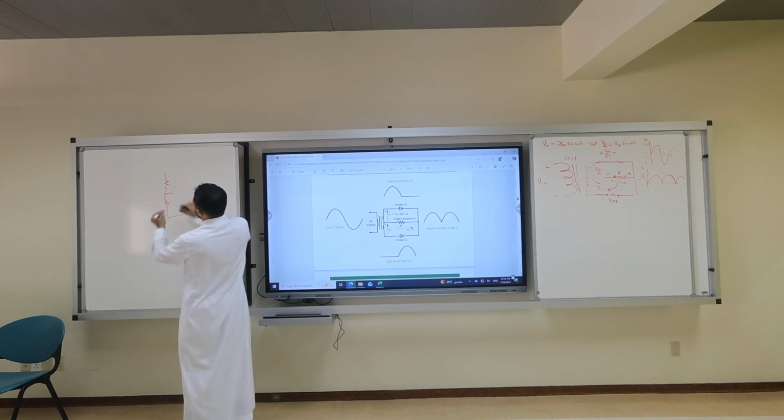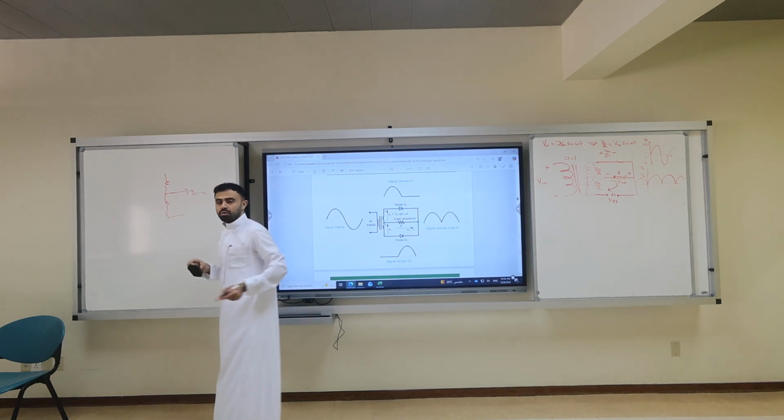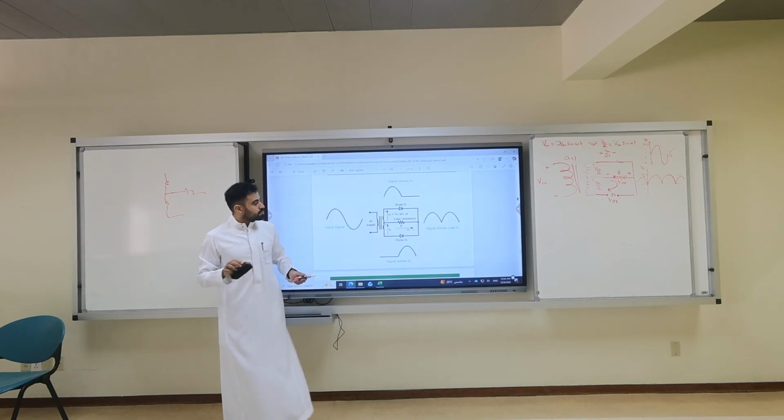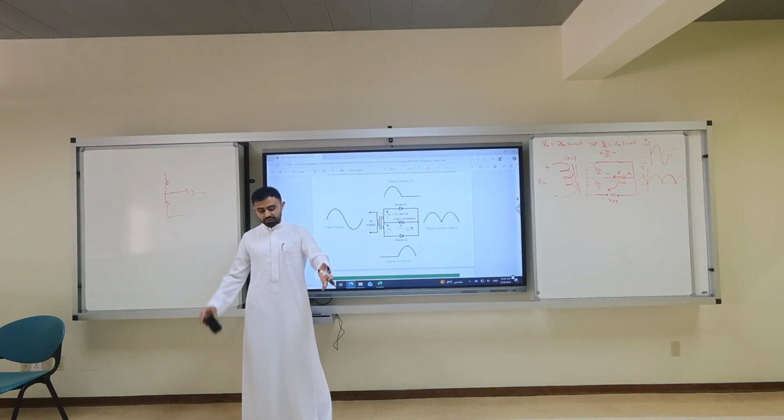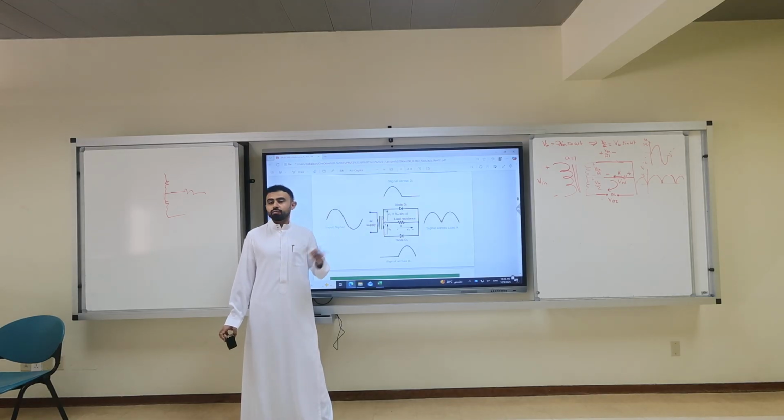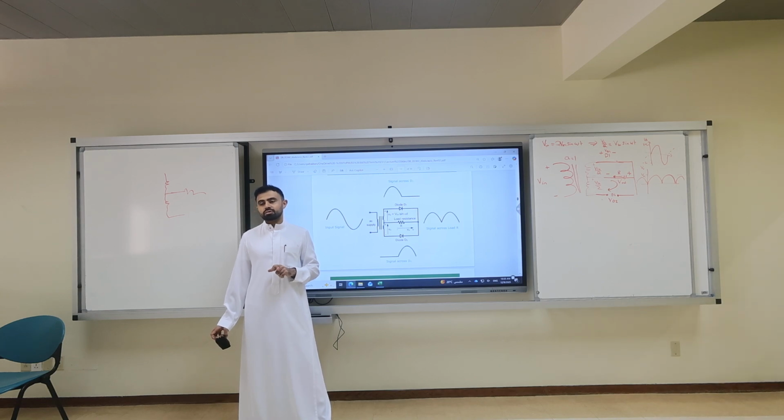You're not connecting it to ground, you're connected to another load. No ground. This system is not grounded. Negative is never the ground. Positive here. Remember in the battery kit, plus 5 and minus 5 volt. Ground, you either connect it at zero voltage drop for sure. You don't connect it at nonzero voltage. Okay?